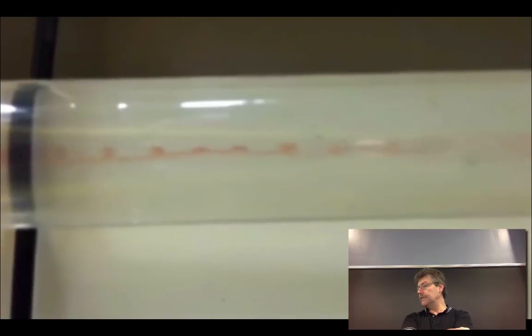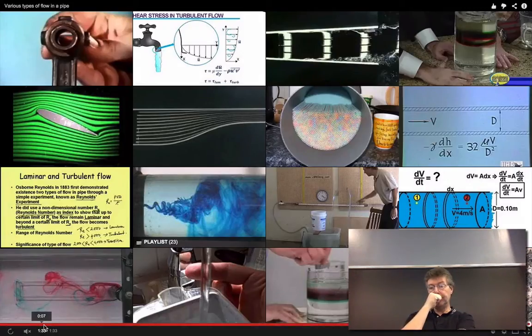I don't know whether you know that some of the salt deposits, subsurface salt deposits in New York State and northern Pennsylvania are used basically as repositories for that, so that when everyone turns their heaters on in New York City at 7 o'clock in the morning, there's enough gas to be able to supply that. So these are just drill holes pushed into the ground, water circulated to the bottom of the casing as the casing is pulled up, so you get these big, long, cigar-shaped caverns in the subsurface, which you put natural gas into, displace water, brine from that to the surface, and then when you want to get the gas, you just put the water back in, and it pushes the gas out, and it goes into the pipeline, etc.